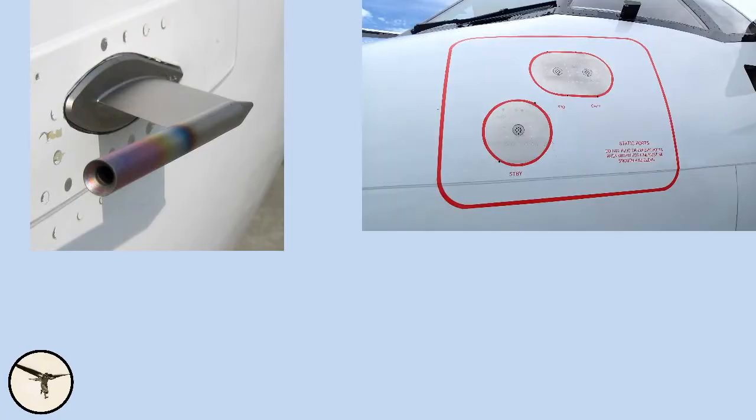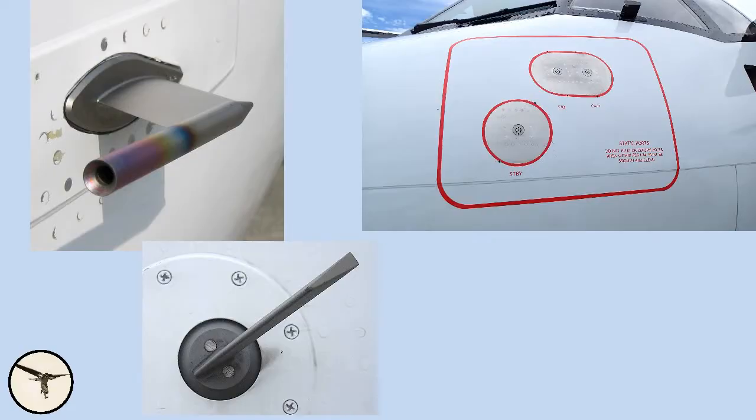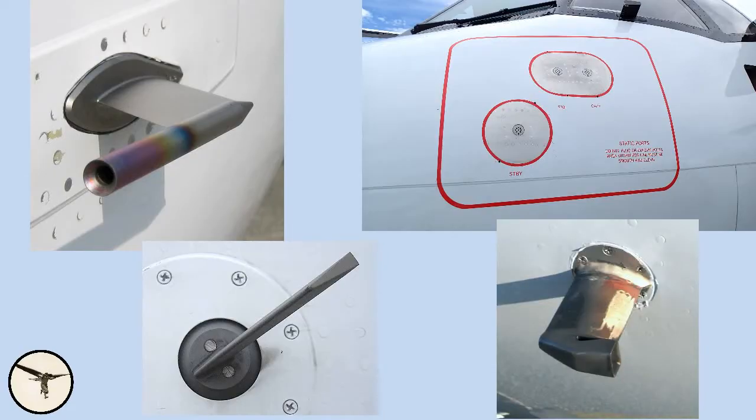Pitot tubes, static ports, angle of attack probes, and temperature probes are heated. Most of the probes are heated by 115 volt AC wild power. AC wild is AC variable frequency. However, the static ports are heated by 28 volt DC power, and the standby pitot tube is heated by AC constant frequency power via inverter number 1, which is powered by DC power.